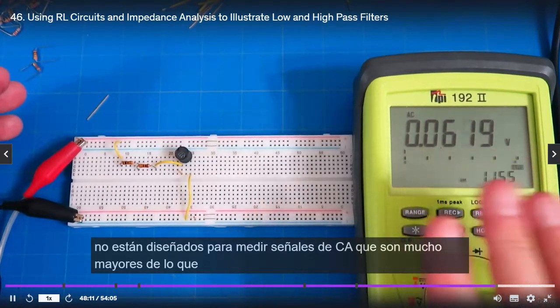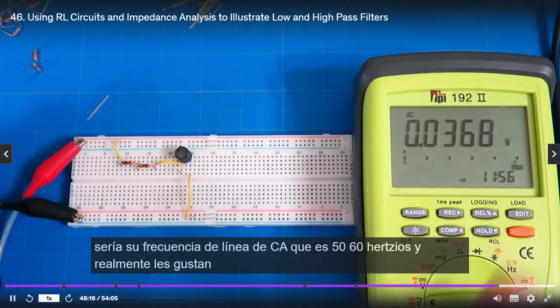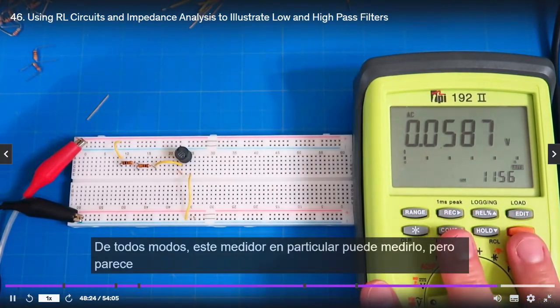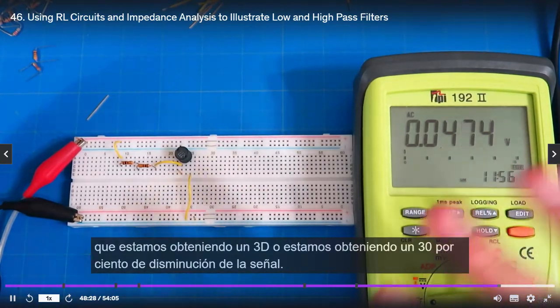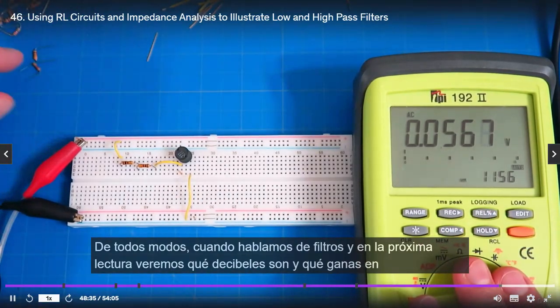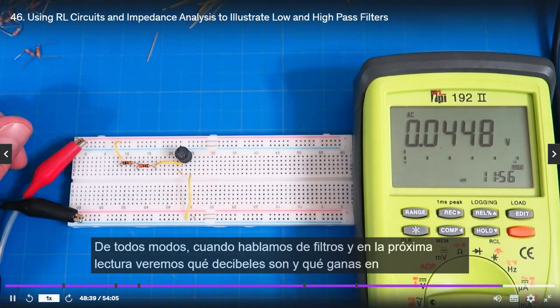These meters are not designed to measure AC signals that are much greater than your AC line frequency, which is 50, 60 hertz. And they really do like higher voltages. Anyway, this particular meter can sort of measure it, but it looks like we're getting like a 3 dB decrease, or a 30% decrease in the signal.